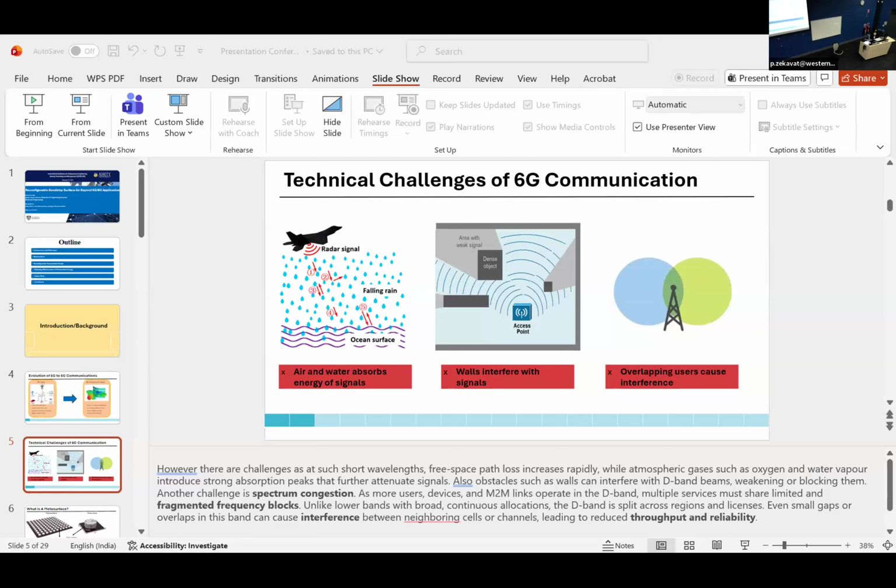I then looked at shielding effectiveness, or I'll just say SE, as this is a critical performance measure that determines how effectively the structure can suppress unwanted electromagnetic frequencies. So SE is defined as the ratio of incident field to the transmitted field, and it can be expressed as the negative of the S parameter transmission coefficients.